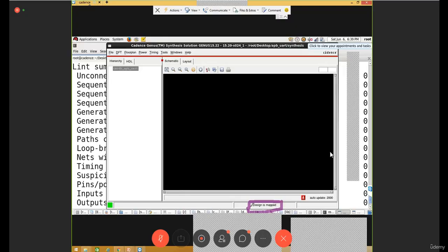It has some AND gate which is of 2 cross 4 or 2 cross 6. In such cases, you will get such errors. It might be an issue with the RTL, it might be an issue with the library, so we can't define which exactly it is. In that case, we need to change the RTL code. Yes, definitely. Okay, thank you.